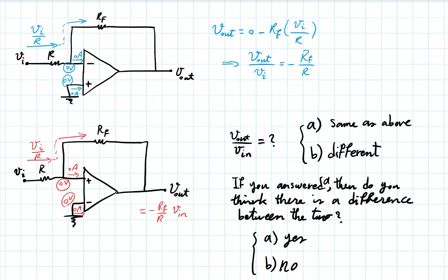I'm assuming infinite gain, and since V out is going to be a finite value, then that divided by infinite gain should give me 0 difference at the input, which is why I have transferred this 0 volts from the lower to the upper input. And then everything else follows from that. Would anyone like to challenge any of those assumptions? And it is an ideal op-amp.